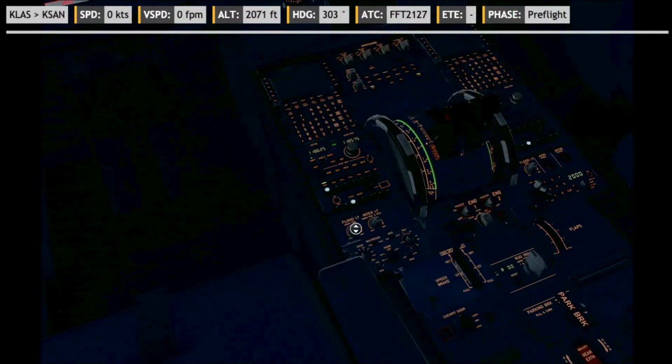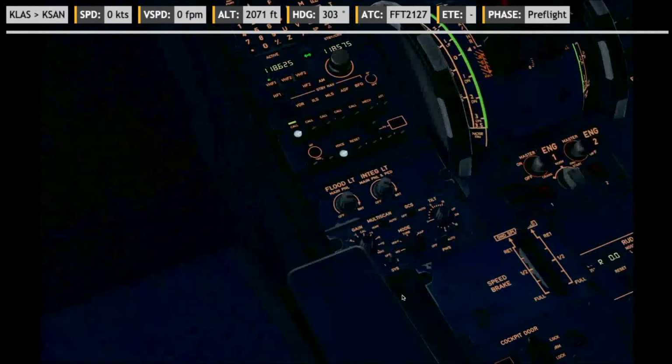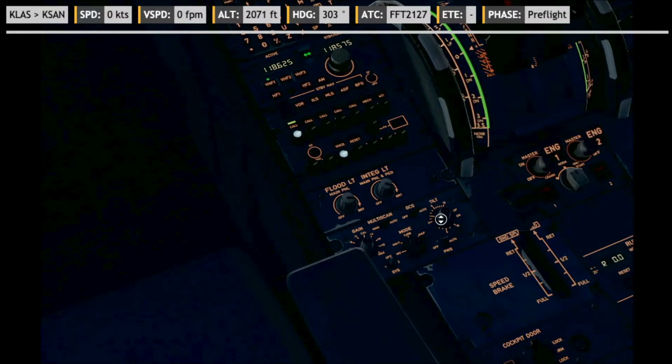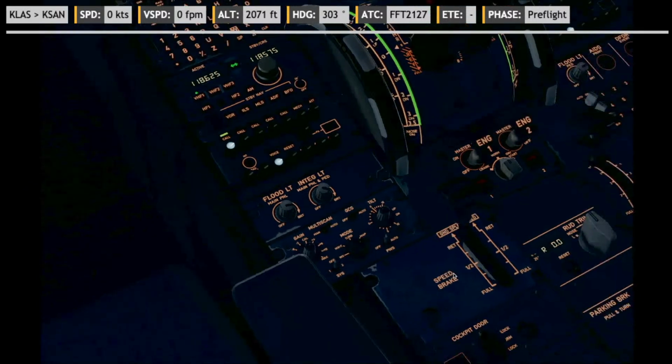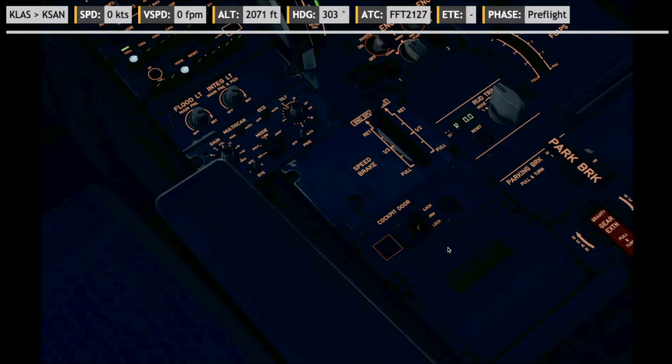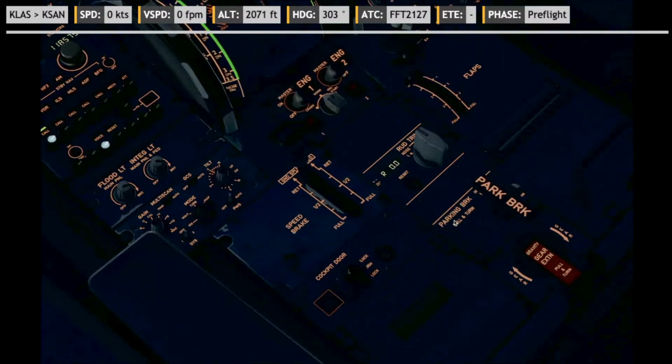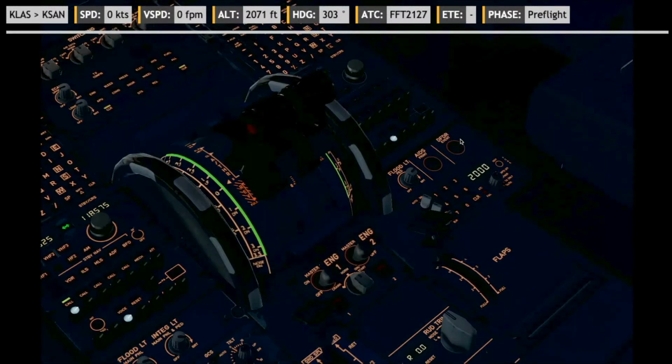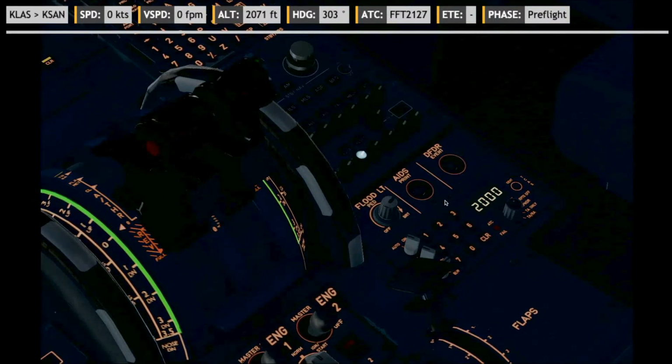These lights on. Weather radar, we'll go auto, 5 degrees up for our initial climb. Off still, and predictive wind shear on. Speed brake as required. Cockpit door, we can lock the cockpit door, or we can have it in normal. Parking brake is set. This is all set. Transponder, we are not using any air traffic control, so I can leave it on the standard instrument squawk of 2000. We'll go on, and in the mode we'll go above for our climb, and then we're not moving yet, so we'll leave it off for now.